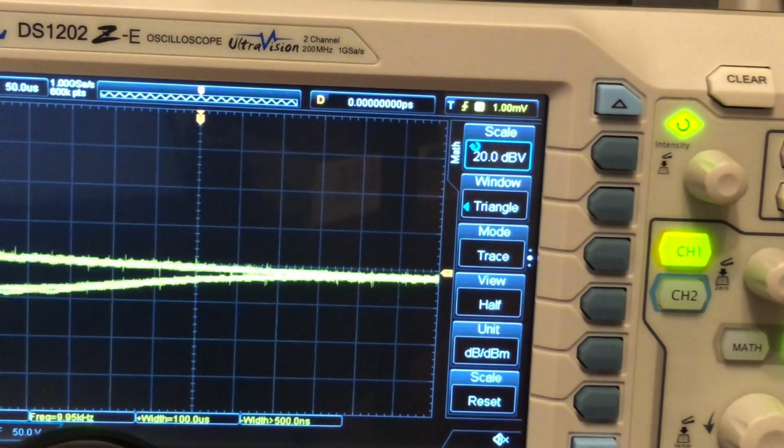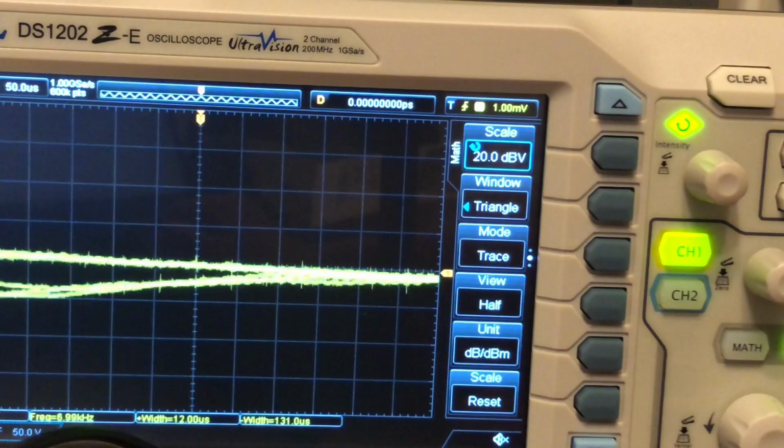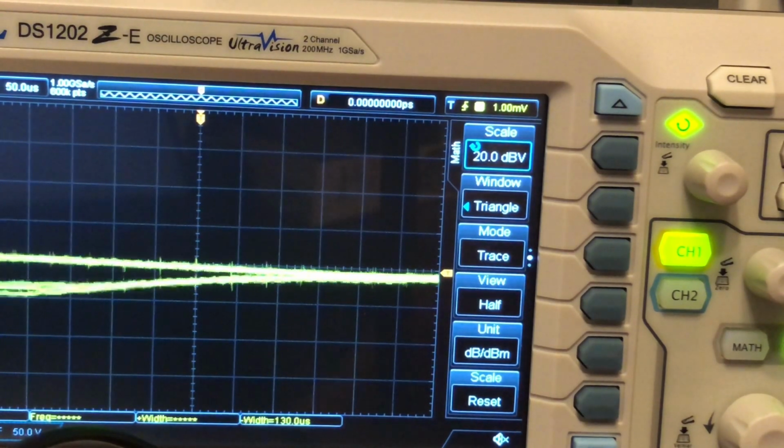The read rules are as follows. If the trigger position is before the start point of the memory, the instrument will read the data of 16,384 points from the start point of the memory. So memory mode is only available in YT time-based mode and not slow sweep mode.